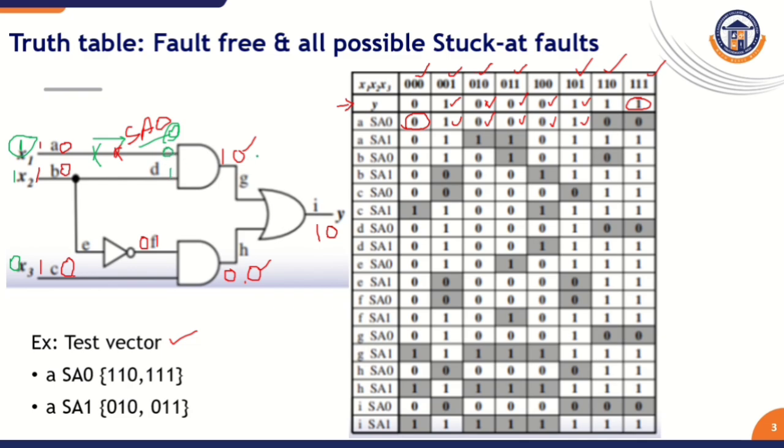So with 0 1, what is the output of this AND gate? 0. But our expected result is 1, because we are applying the value 1 1, but this 1 is changed like this. According to this input combination it generates the output like this. So this goes to this inverter. The inverter output value changes, and the output is 0.